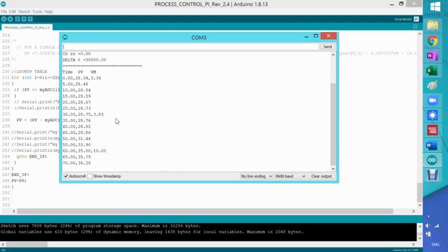All right, so that's how this works. Now, the data that I got for this thermistor is from somebody else. It's not my data. It's not my thermistor. So every thermistor needs to be calibrated for the range that you are working on. Now, what happens if you are out of the ranges?